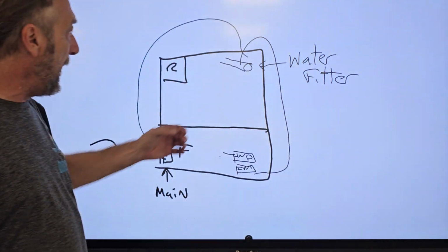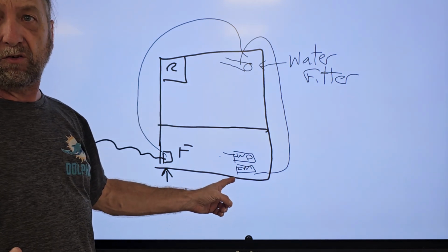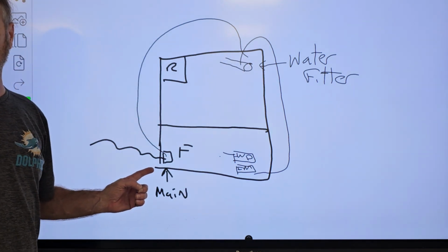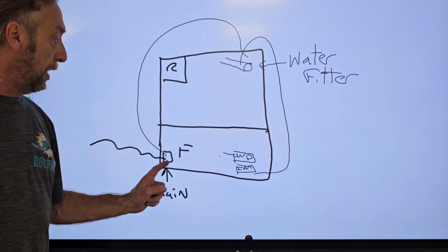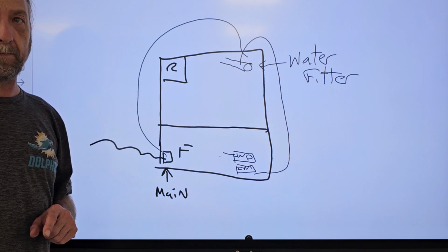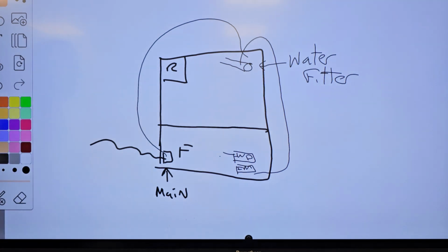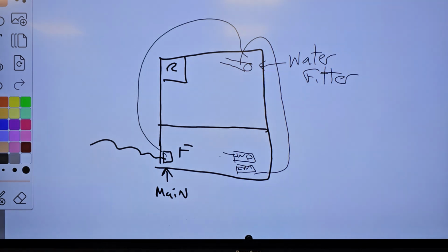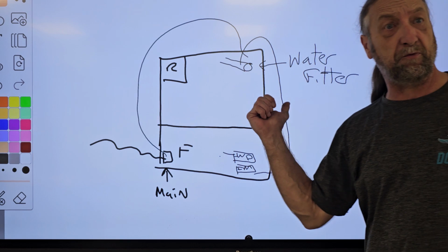But I have guys tell me, I put my cup in the door and no water's coming out. Well, it could be this water valve, but then you see this water valve goes to the filter, and this filter goes to another water valve. Why do I have a valve here and here? That filter's on the bottom by the compressor. It's not even inside the fridge. The only thing inside the fridge is that filter. It goes in the filter and right back out.